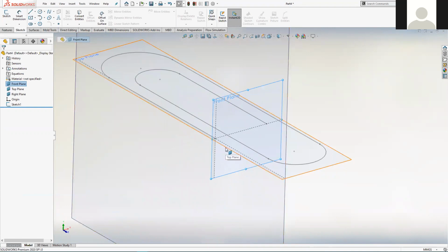That's because the profile shape, we need to sketch at 90 degrees to it. And rather than have to create a new plane, which we could do, it's easier just to use one of the primary planes. So that's why that line there terminates at that front plane, so that this profile shape, we can use the front plane to sketch on.